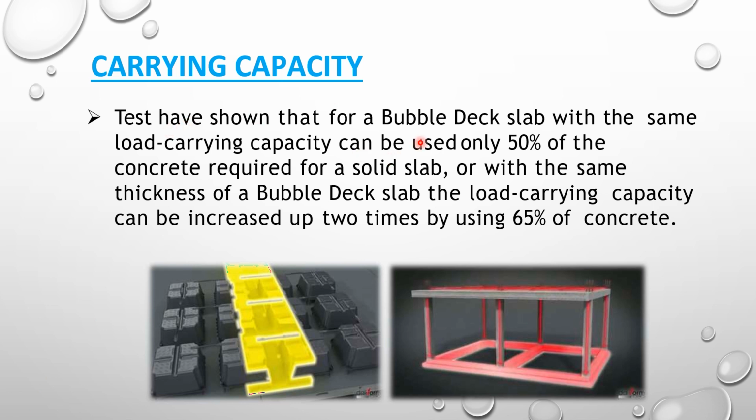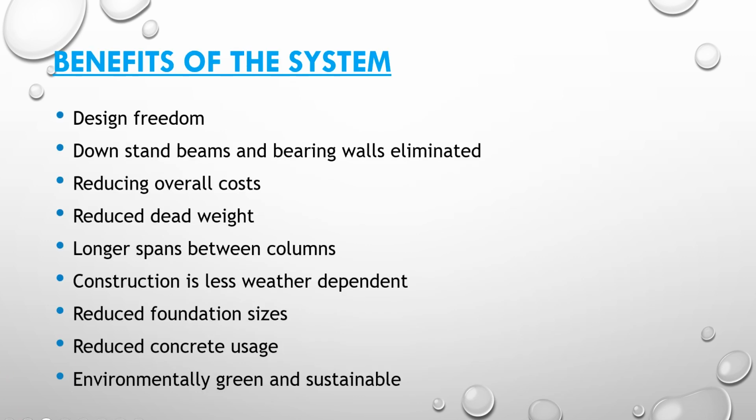Tests have shown that for a bubble deck slab, with the same load bearing capacity, only 50% of the concrete required for a solid slab is used, or with the same thickness of a bubble deck slab, the load carrying capacity can be increased up to 2 times by using 65% of the concrete. So it is helpful in carrying capacity also.